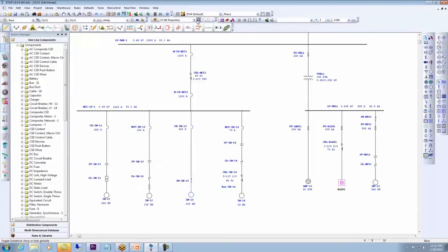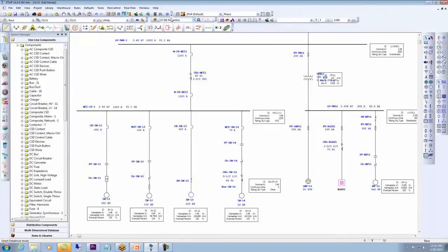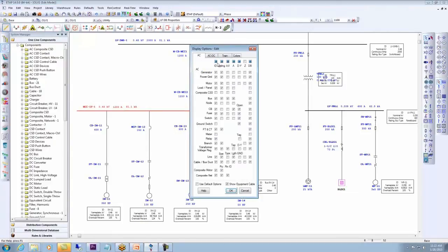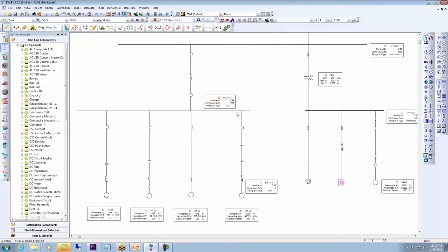This option here has me globally turn on the data block selected. Now you can see that we have two options. We can keep the annotations that we previously had along with a newly constructed data block, or I can simply come in here and undo the options for display options and only show the data block. So it's up to the user. You can do display options, you can do data blocks, or you can do a combination of both.